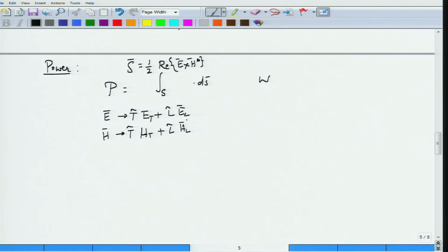What you can see is that since the power needs to be transmitted or taken from one place to another place on the waveguide, what is interesting is not the longitudinal components, but only the transverse components, right. Since these are the only things which are interesting and these relationships are already known in terms of the impedances, you can safely substitute for the impedance, relate E and H, and obtain this expression. What we mean here is that Ex is given by Z Hy and Ey is given by minus Z Hx, right, because Ex by Hy is Z and Ey by Hx is equal to minus Z.